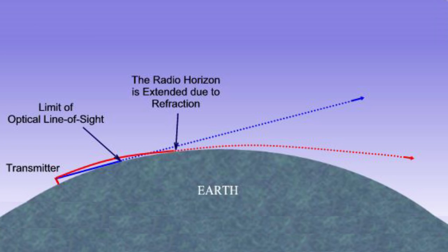You can extend the range of your communications on VHF and higher frequencies by increasing the antenna height. 10 feet of antenna height is like doubling your power output. This is why a repeater on a high point is so effective in extending range on VHF and higher frequencies. Another thing to do is pay attention to your antenna and feed line losses. Losses are much higher at higher frequencies for the same given length of antenna feed line.